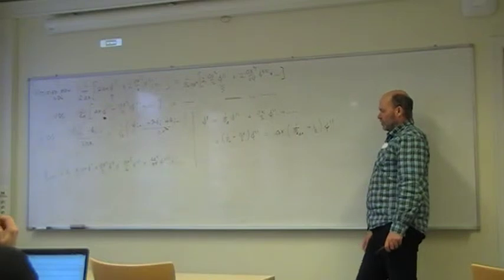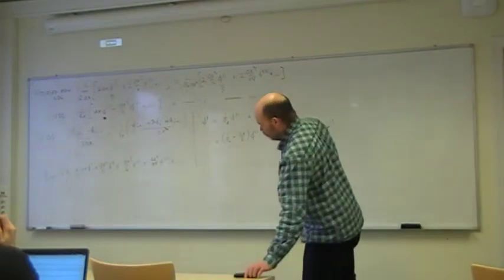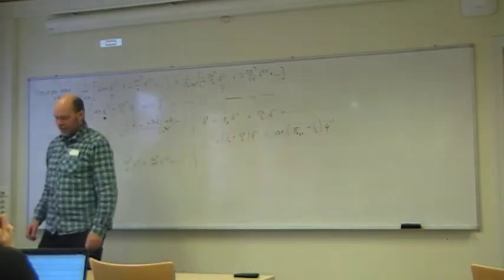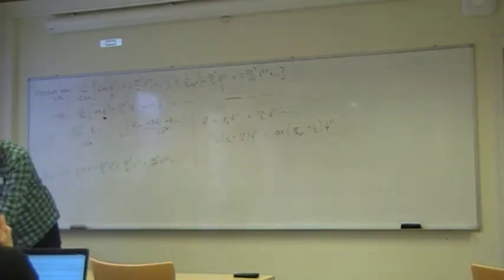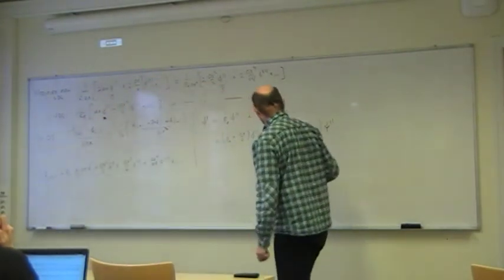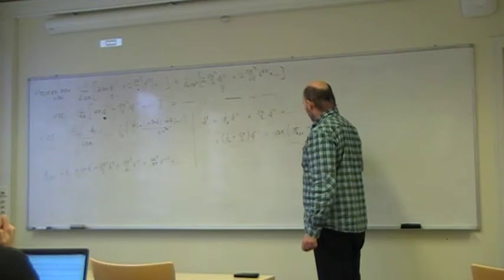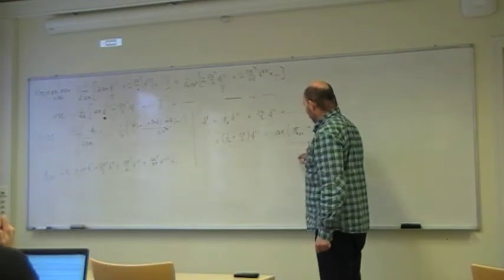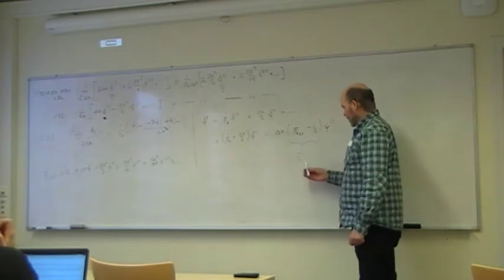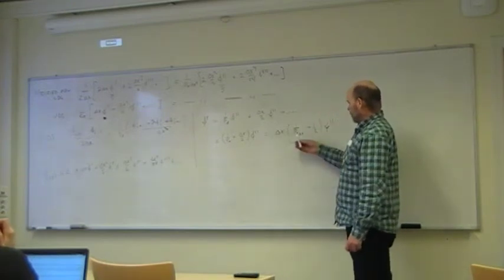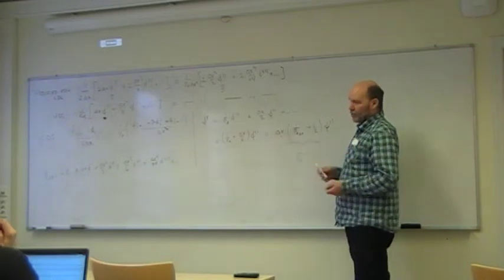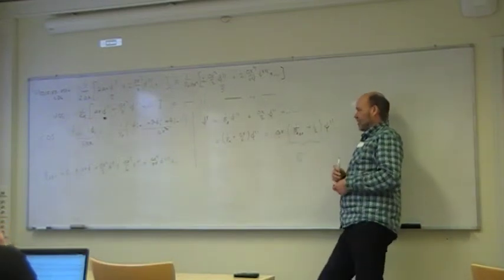Of course, you could do the trick that you wanted one Reynolds number, and then you say, I want to use this upwind scheme because I know it's stable. Okay? So then you have to call this one your Reynolds number, and then calculate what it should be. Here it is actually possible, but remember this is a one-dimensional problem, so constant delta x's.